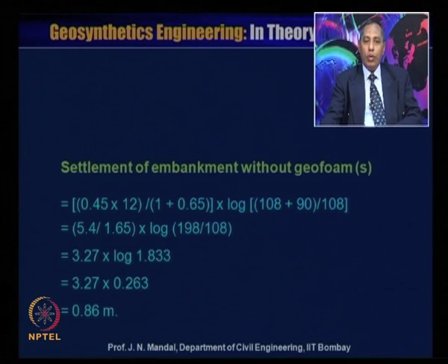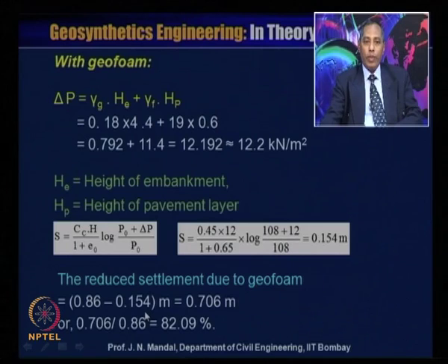So you can see when you are using the geofoam, settlement is 0.154 meter. When only soil is used without geofoam, the settlement is 0.86 meter.